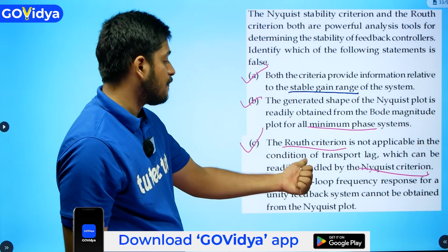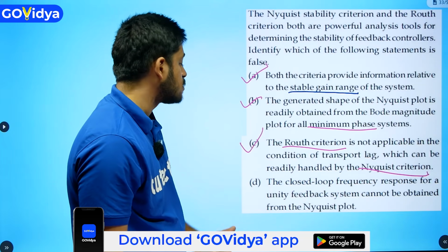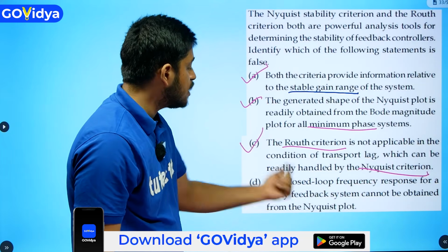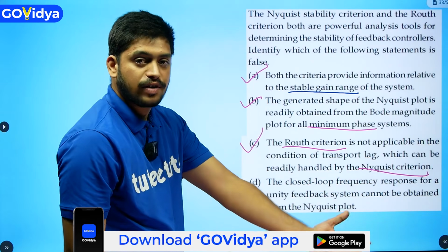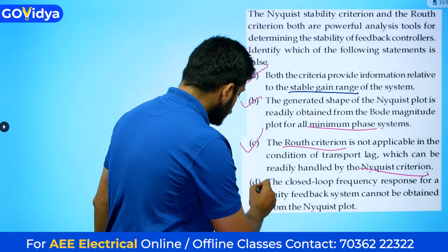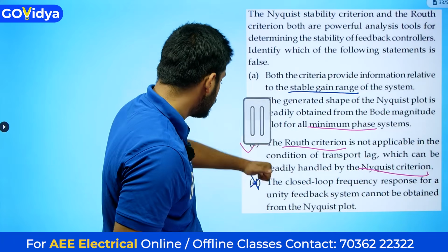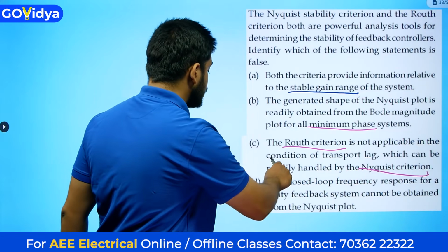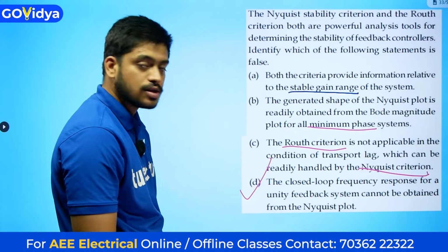The closed loop frequency response for a unity feedback system cannot be obtained from the Nyquist plot. Why? We can easily obtain a closed loop frequency response, which is nothing but we can determine the transfer function. We can analyze the transfer function through Nyquist plot also. So this is the wrong option. But here he asked for the false statement, so as per the false statement, this is the right answer. Okay, this is the false statement among all the given statements. Understood? Next question.